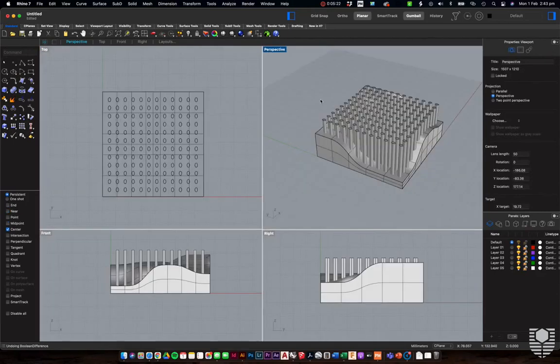All right, let's have a look at some of the incredibly powerful tools we have now that we're working with solids. So what I've got here is a bunch of different solids all working together. And effectively what I'm doing is creating a tile. I'm going to play around with what we call a boolean to bring me different options, different variants, different iterations for that one tile.